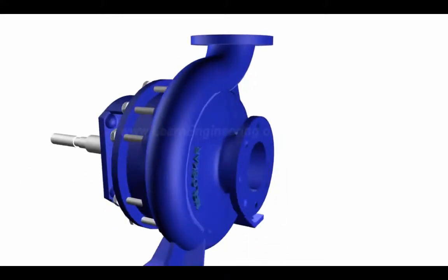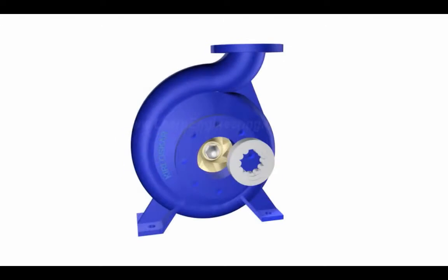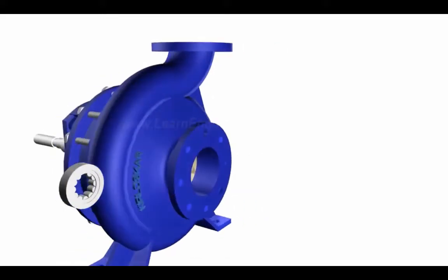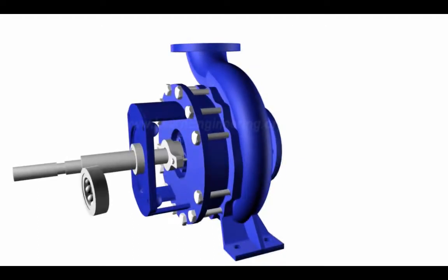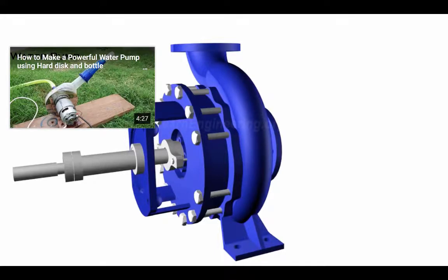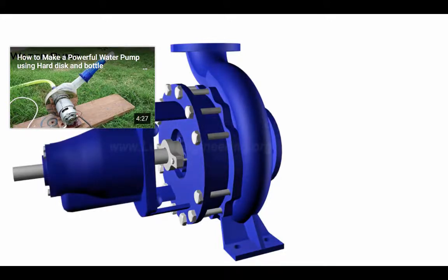The impeller is mounted on bearings, but at the suction side of the impeller, it is not advisable to fit a bearing since it will block the flow. So bearings have to be fitted at the other end. This means the impeller is mounted like a cantilever. For high flow rate pumps, a bearing housing with cooling oil is necessary for improving the life of bearings.